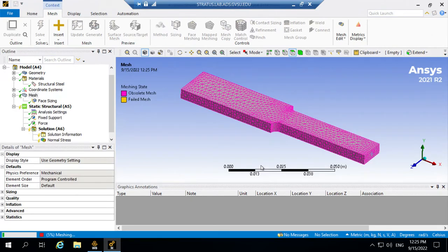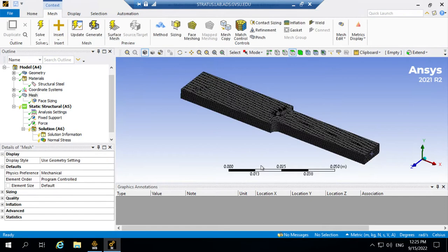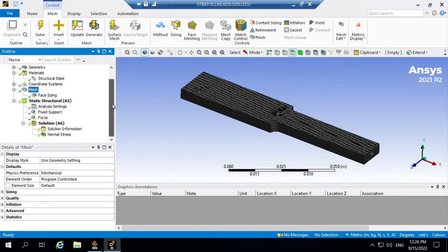But when you are doing this, you gotta be careful about not hitting our software license. Our academic license is limited to 20,000 I think elements. So if you hit that, then it's not going to solve it for you.